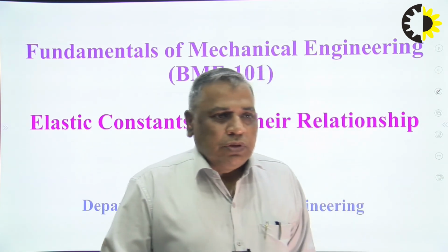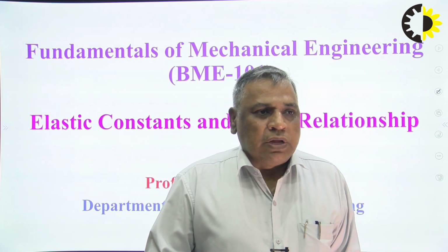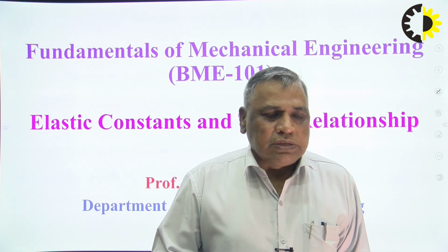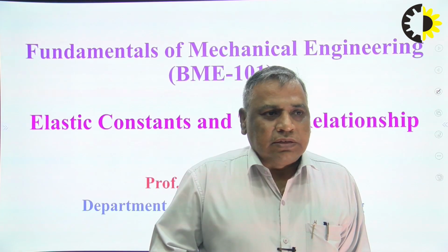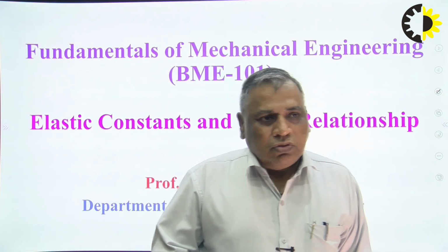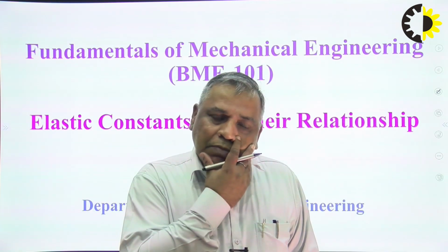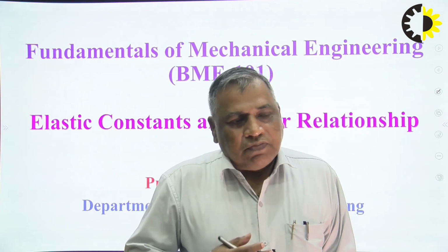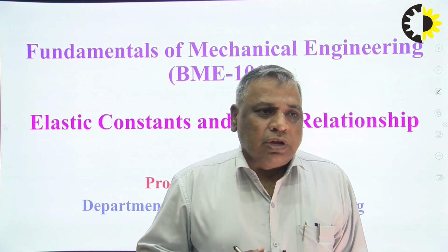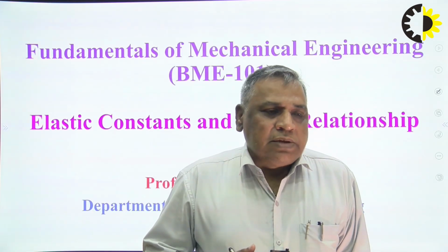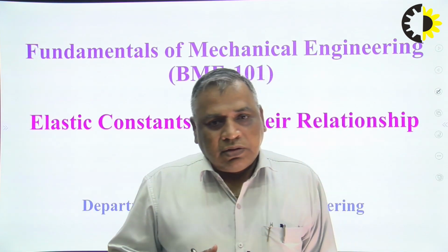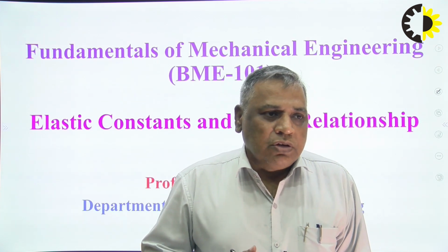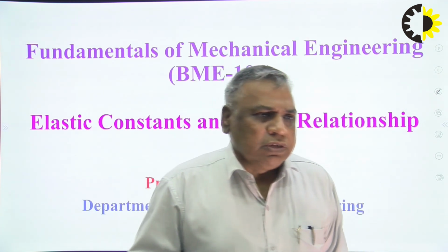Everyone of us is well aware of Hooke's law. Hooke's law states the relationship between stress and strain, that is, stress is directly proportional to strain. It is applicable up to the limit of stress and strain up to which there is a relationship. If I say Hooke's law is valid up to the elastic point, it is accepted, but more precisely, Hooke's law is valid up to the proportionality limit, because there is a linear relationship between stress and strain.